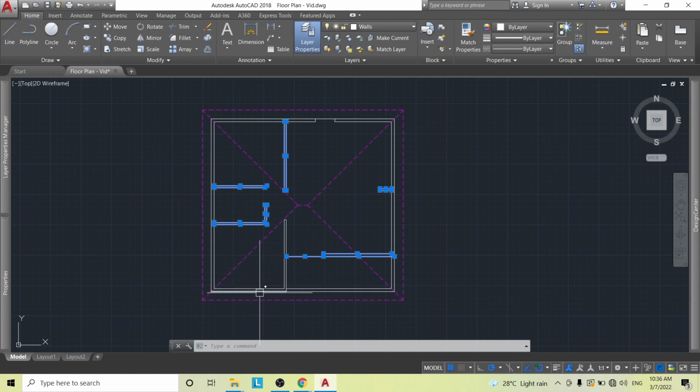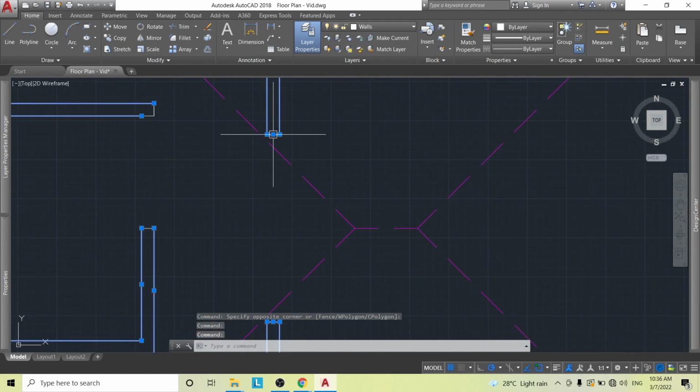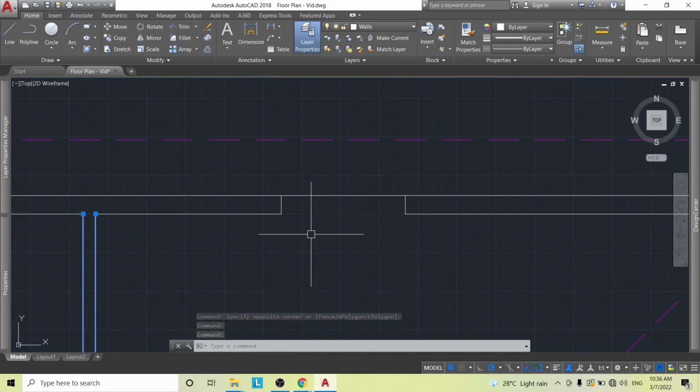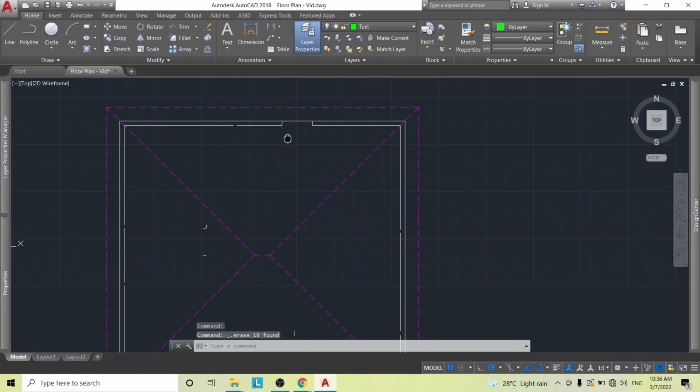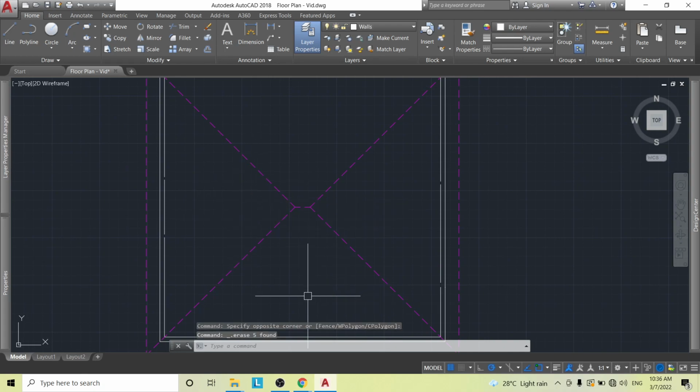So we want the outline of the building, like what we have here. So delete all of these interior walls. There's one in between there, this line in between there, and then just hit delete. They're gone. So now we see some parts that are left back, delete them too inside.